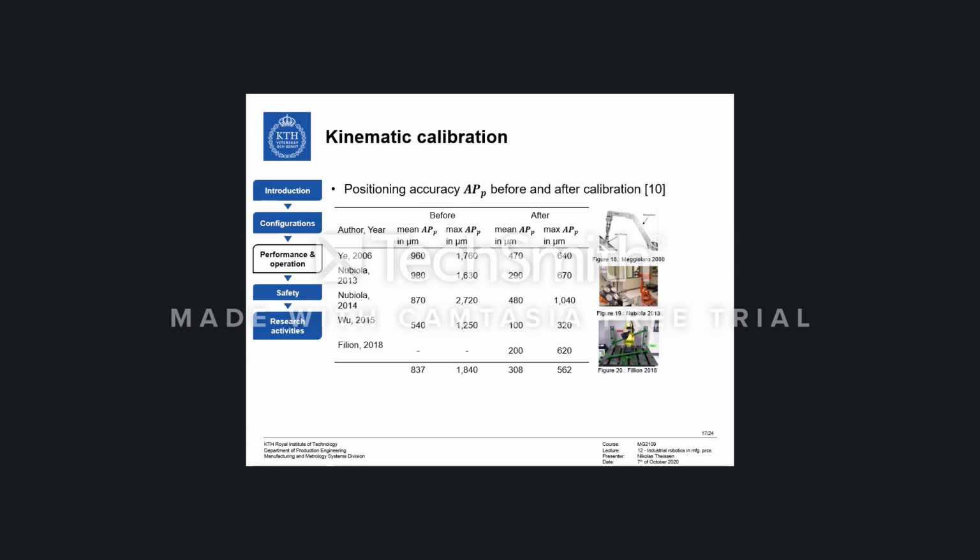And this is useful because if you have increased your accuracy to the level of repeatability, you can rely more on offline programming on the computer, while at the same time creating transferable task programs so that you're not dependent on adapting the task programs on the individual manipulators.